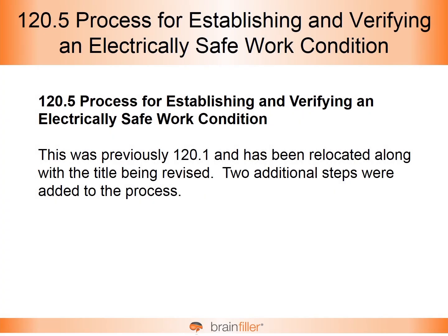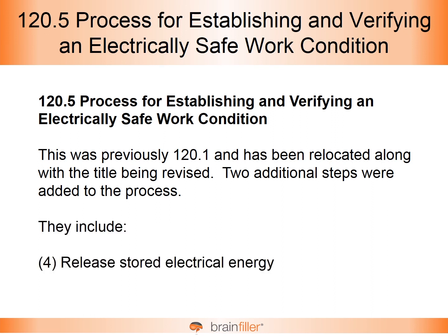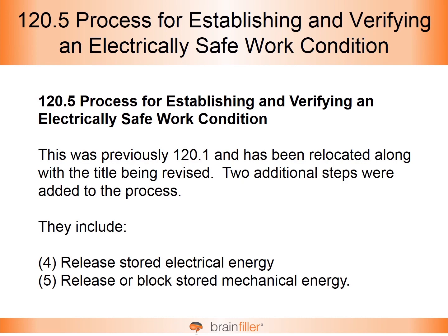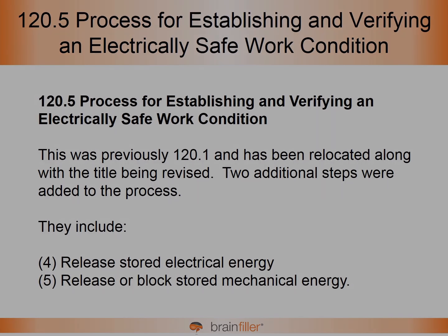The process for establishing and verifying an electrically safe work condition has been relocated from 120.1 to 120.5, and in addition, two additional steps were added, which include release stored electrical energy, such as from capacitors, and release or block stored mechanical energy.